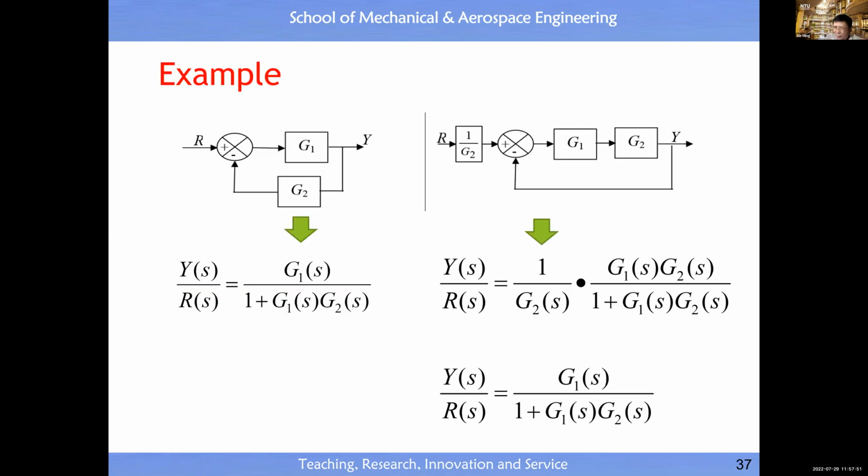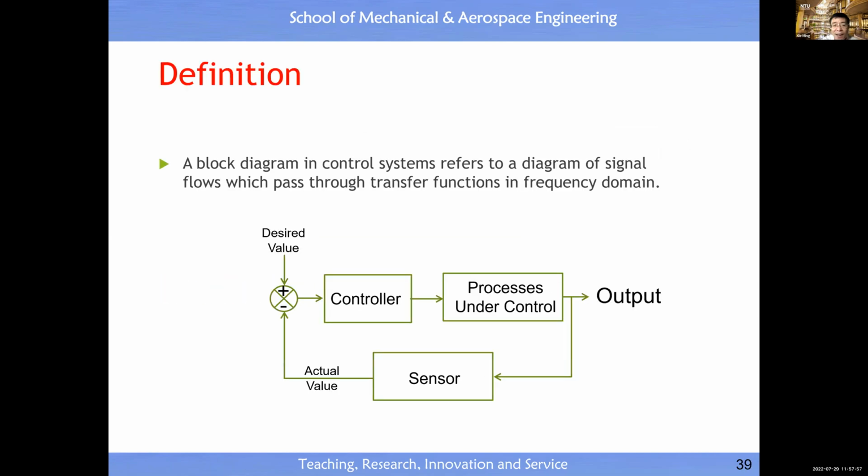With transfer functions, we can draw the block diagram. Here you see we can visualize a transfer function. What is the block diagram? For each module, we derive a transfer function, then we draw the relationship among the signals. These signals come from the output of each module, and they could become an input to some of the other modules. So the signals from the outputs of these modules could be connected together. You treat it as a signal diagram. That will help you understand a lot of things.